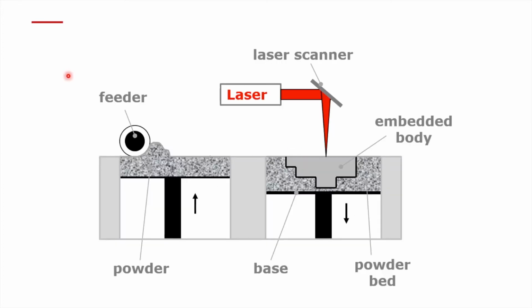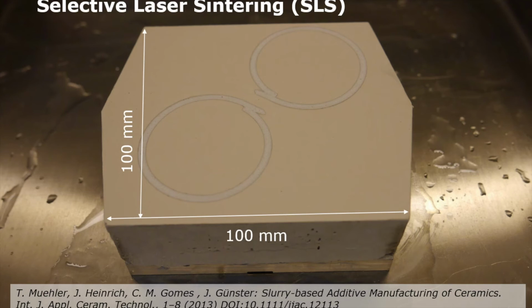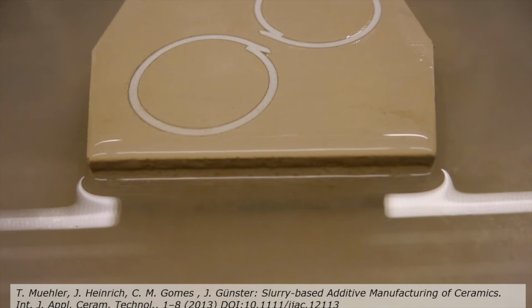Now we combine the layer-wise slurry deposition with the selective laser sintering process. This is how a laser sintered part from the LSD process looks. You see the powder bed has a high density, it's relatively tough, like a green body. It depends, of course, on the binder and the slurry. And here you see two espresso cups which are laser sintered into this block. The block consists of 360 layers, each 100 micrometers thick. In order to release the parts out of this green body block, you place it into water and you start to wash out the parts.